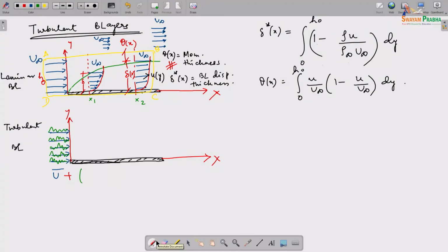Now, of course, in the boundary layer case, it has been experimentally proven that the v component of the velocity is negligible. Its effect on the boundary layer is negligible, that is all. So, that is why the only velocity component which becomes dominant in the boundary layer studies becomes the axial component of the velocity. So, essentially the velocity, okay, the free stream, so the free stream is all this.